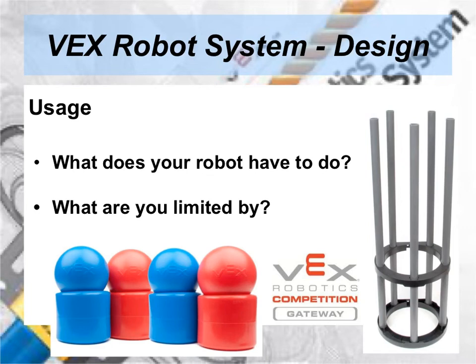For the VEX competition, one of your limits is size. Usually VEX robots can only be 18 inches by 18 inches by 18 inches. I've been to competitions where a robot has been off by 1/4 of an inch and couldn't play, so judges are very strict. Other considerations are how many motors you can use, how many batteries you can use, and the weight of the robot. Understanding your limits will help you design a better robot, a robot that will meet the competition task.